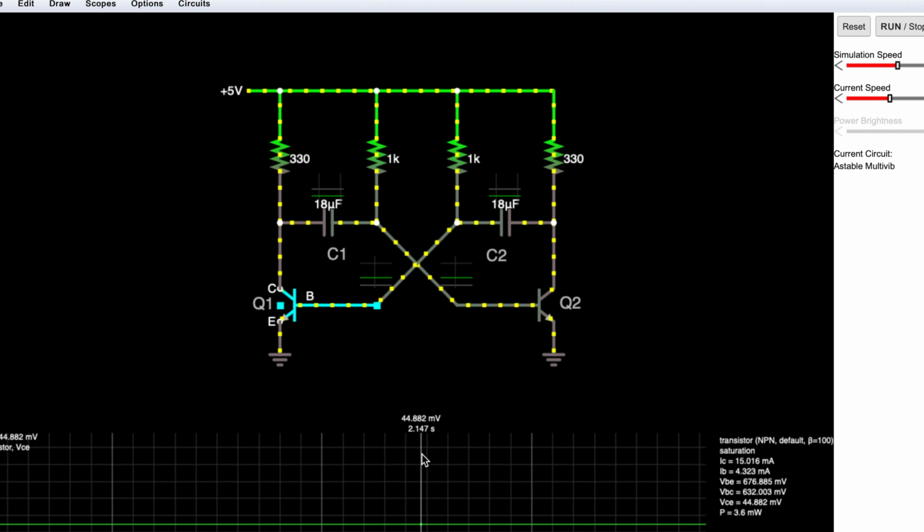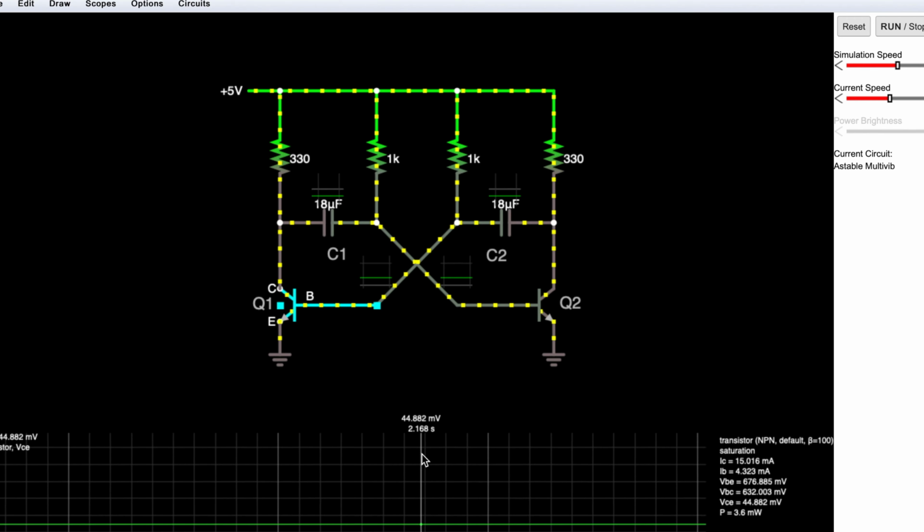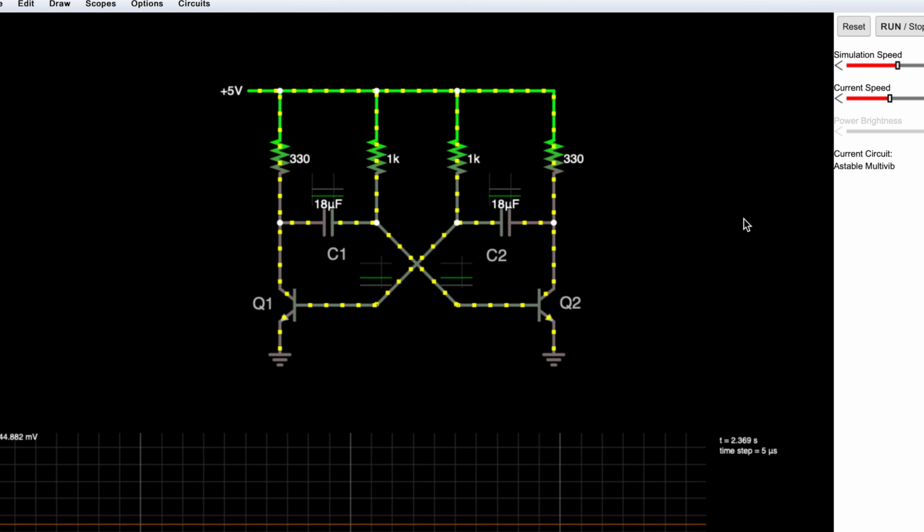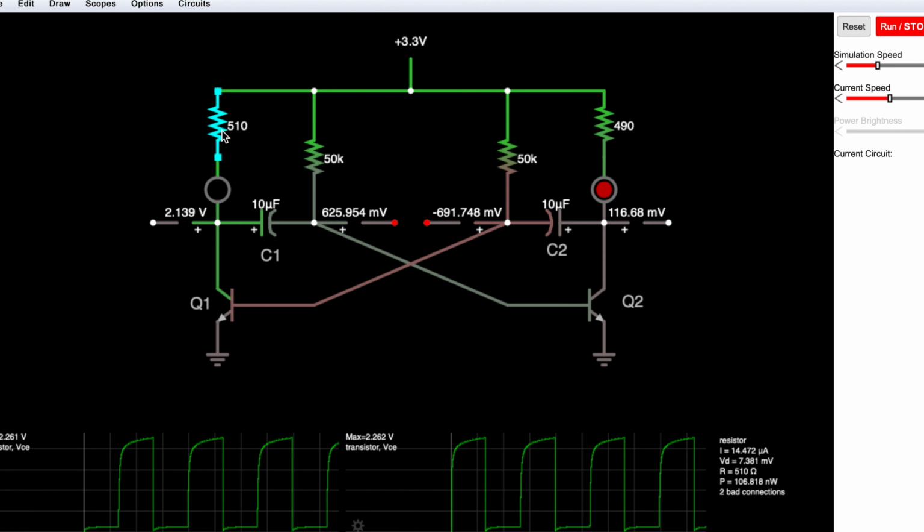In real life it works because not all components have the exact same advertised values. Some components will be slightly lower or higher. In fact, most electronic components will have a tolerance advertised along with the values. To avoid this, we of course will make R1 and R4 slightly different. So here, instead of having 500 ohms on both sides, this is 510 and this is 490. This is again within the tolerance limit. In fact, this is 2% off. So we're assuming that R1 is 2% above value and R4 is 2% below value.